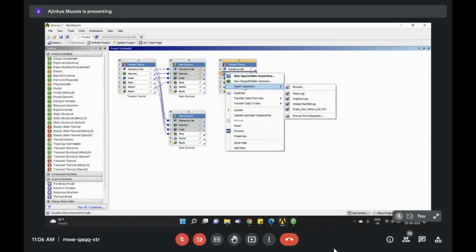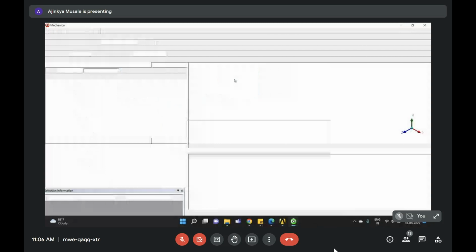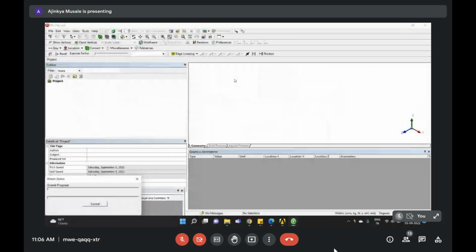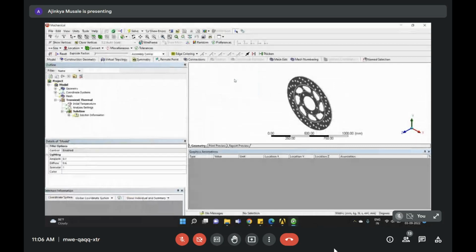That's why I haven't told you until now, but as you are now very familiar with this, I told you the shortcut. So by this way also you can import your body, but the criteria is it should be solid. Right. Now I need to check units. Fine, they are in millimeters.